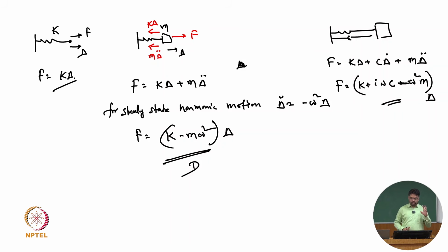So if you see, inherently the dynamic stiffness matrix is very similar to the static stiffness. But the important point is that the dynamic stiffness matrix contains the effect of mass, effect of stiffness, and how they are changing with the frequency. So the static stiffness matrix, if the stiffness is constant, will remain constant, whereas the dynamic stiffness matrix will no longer remain constant, and that is frequency dependent. If the frequency is changing, the dynamic stiffness matrix can also change. That is the important point.